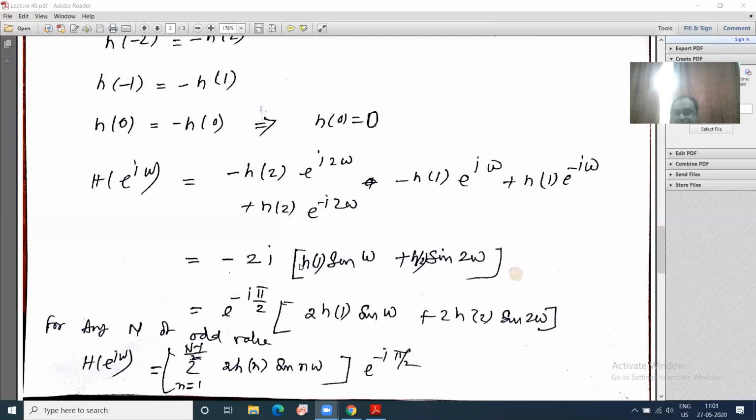So if I say the Hilbert transform x cap of omega is minus j times signum omega x of omega, then minus j x of omega is available with you. Once this is available, we can substitute the value of signum omega to get the Hilbert transform. Signum omega means for omega greater than 0 it is 1, and for omega less than 0 it becomes minus 1, right? You have studied this in SSB-SC, single sideband suppressed carrier, and in your signals and systems course, in the 3rd semester and 5th semester.